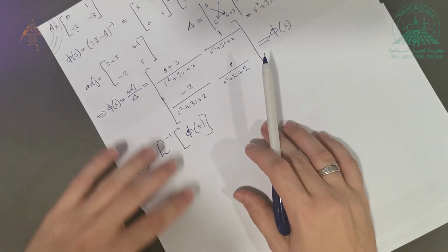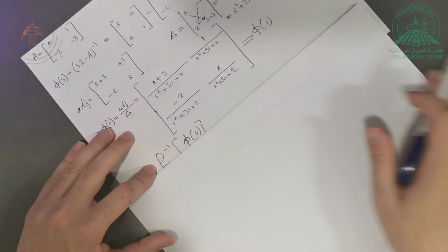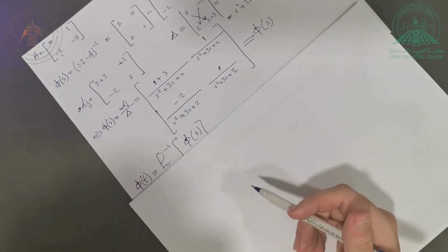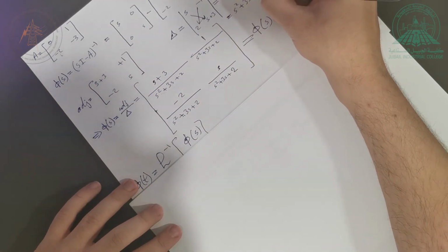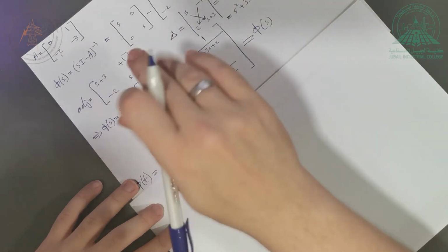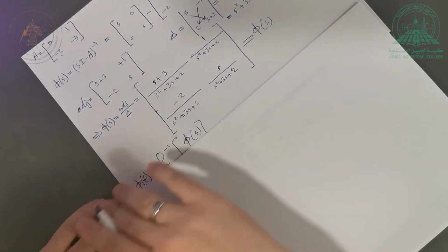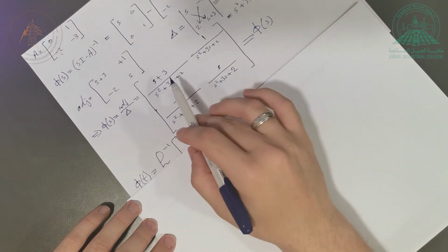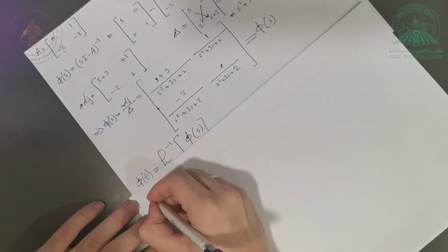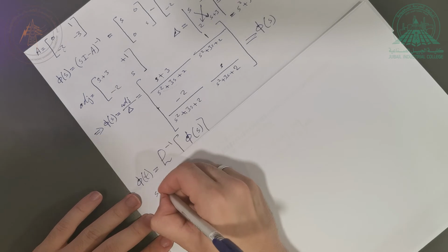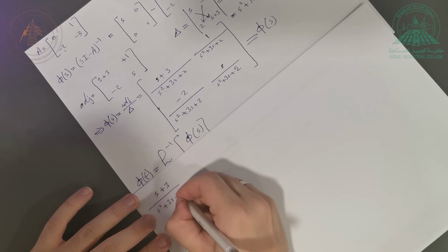Okay, so this is Φ(s) that I have here, and I need to get each one of these. Remember, in this case it would have been better to decompose this, but I wrote it in this form on purpose, so that you can see that when you reach this point, you need to factorize the denominator in order to apply partial fraction expansion. So you do it step by step. First, you do this one here: (s + 3)/(s² + 3s + 2).